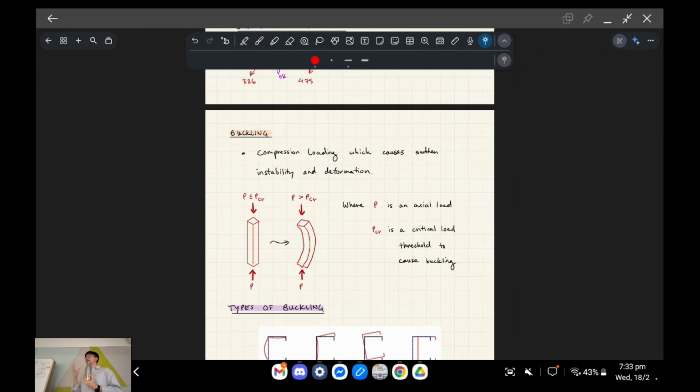Yeah. It's a pretty unique feature of steel structures that people try to get the most bang for their buck, I guess, in terms of choosing the most slender member possible to achieve some result. And it's because steel is very expensive, right? For concrete, you can just cast a larger block of concrete. It's not going to buckle if it's larger, right? More akin to this shape, right?